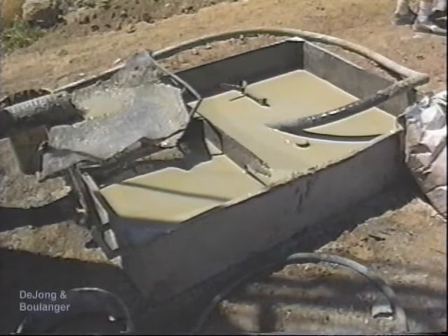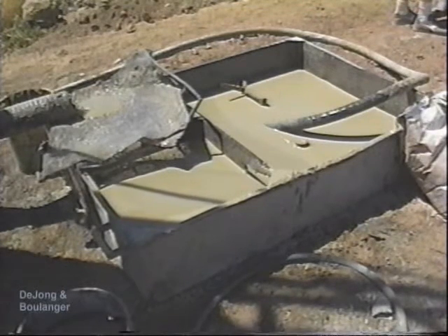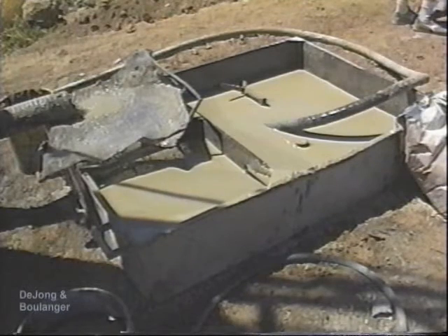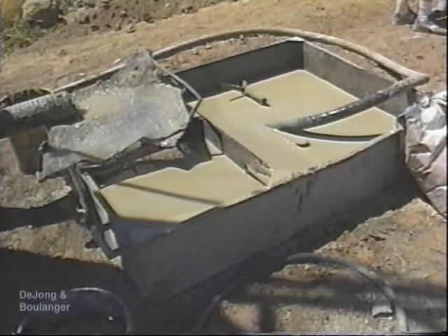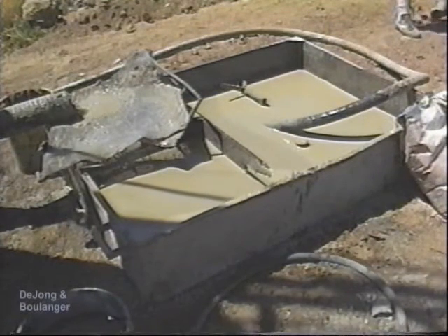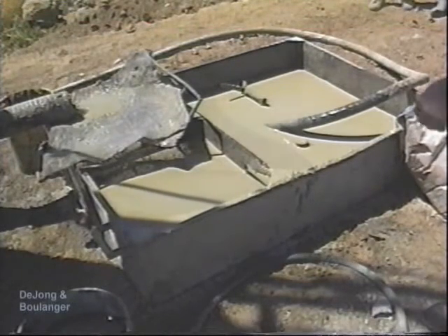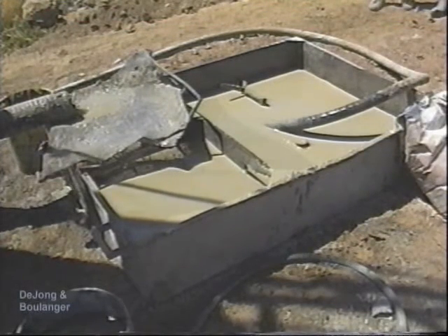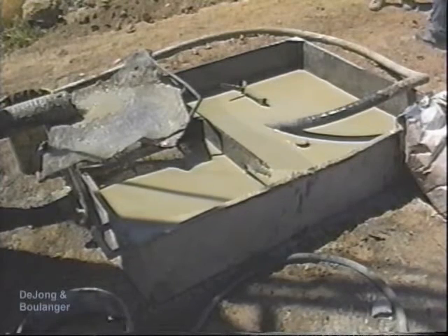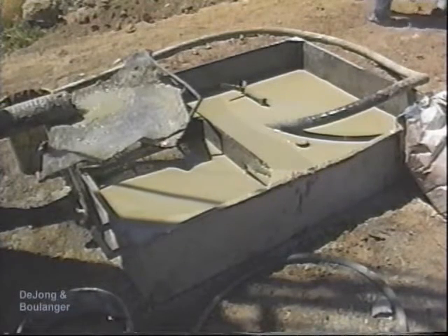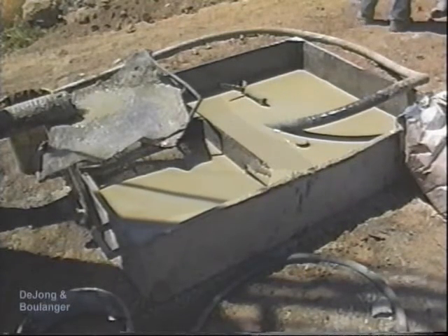The drilling mud also supports the borehole walls, and thus uncased holes can remain stable in sands below the water table. If a piezometer is going to be placed in the borehole, biodegradable products may be used instead of bentonite mud. Biodegradable products avoid the permanent sealing effects that bentonite mud has, and thus won't adversely affect the piezometer's performance.